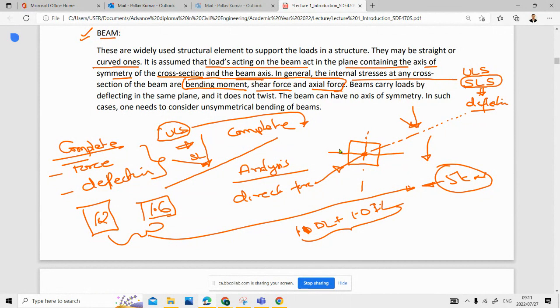So that is what you need to understand as a structural engineer: while analyzing your structure, you need to use your ULS condition. You can't analyze it for the normal condition of the load which is acting on it, and then design it. It will be a disaster. Whenever you are analyzing in a real situation, you calculate all the loads on the structure, use your factor, and once you have used your factor, whatever load comes, you analyze for those loads and then you design for it.